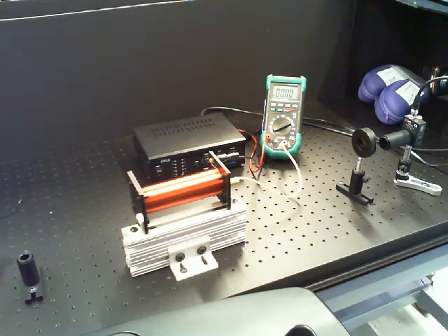Even if there was a noise signal at, say, 45 hertz, we can reject all of the 45 hertz signal as noise if it doesn't occur at the correct phase with respect to our drive. And you'll understand a bit more what that's doing when you try and program up your own lock-in amplifier using LabVIEW. And so again, read the lab manual carefully for what a lock-in amplifier does.